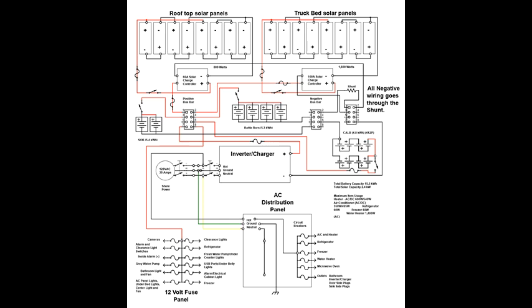Please note that the schematic is shown as a 12 volt system only because those are the components that I already owned, and each of these components were taken from some other previous project. If I were starting from scratch, I would have designed a 48 volt system. And that is also what I recommend for a system of this size. If building this from scratch, it would be a smaller, lighter, more efficient, and less expensive system if you go with the 48 volt recommendation.